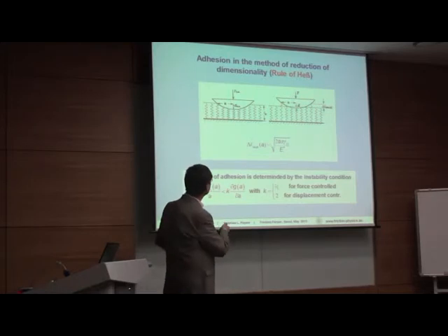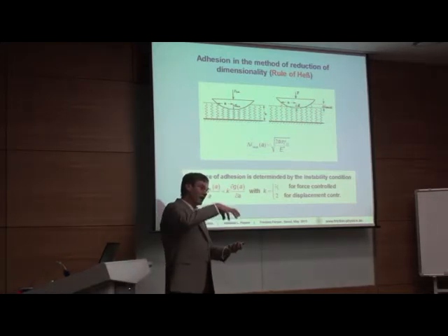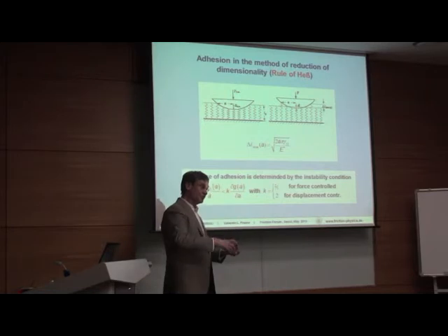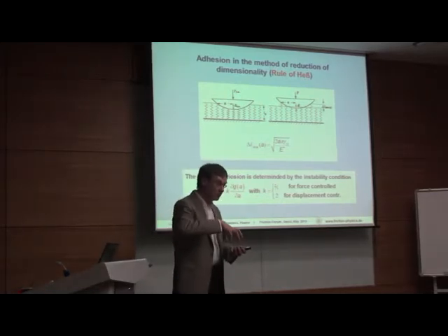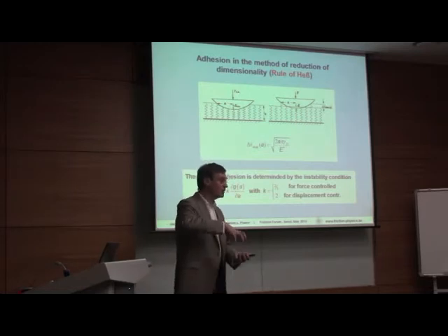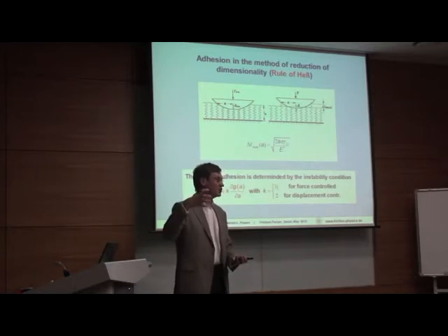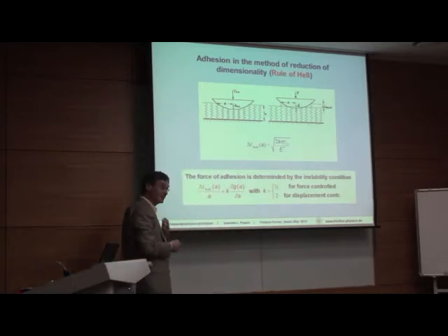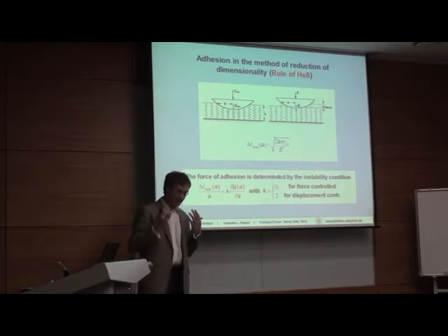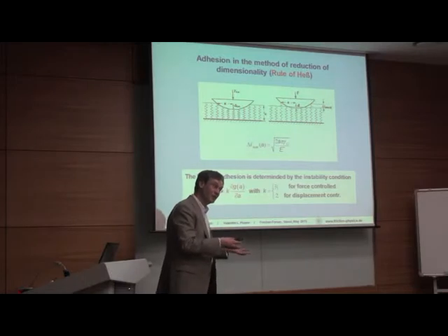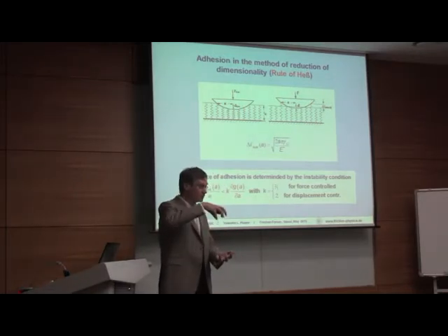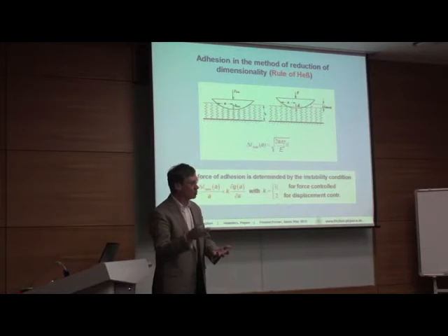And this is now for arbitrary position, but if you only need the adhesion force, and the adhesion force is the point of instability. You pull, and then at some moment it gets unstable and detaches. The condition for the instability is very complicated to formulate 3-dimensionally. You have to have this force displacement relation and look where it gets unstable.